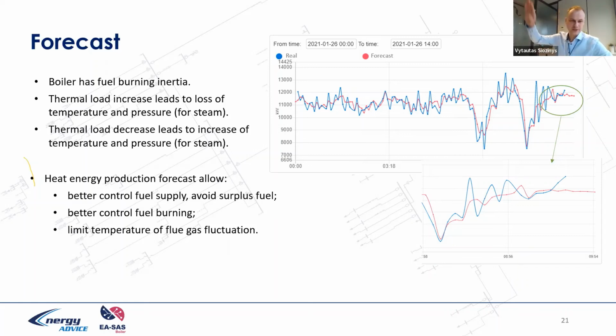If you increase thermal capacity dramatically, we should put in extra fuel, but it has inertia. And if thermal load increases, it leads to a reduction of the temperatures, probably coming near to the dew point of these bad gases, or, if you have a pressure system, to a reduction of the steam pressure.